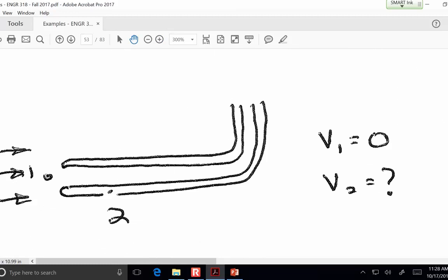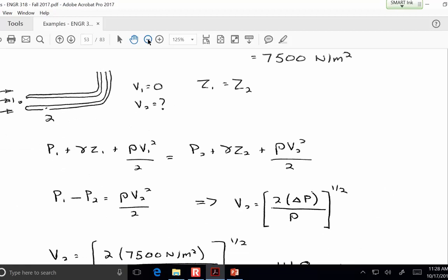A better location would be just on the outside, because inside the pitot tube conditions are static. There's no movement of fluid inside the pitot tube. Just on the outside of the pitot tube is the passing-by wind speed that we're trying to calculate. So I'll adjust that drawing.